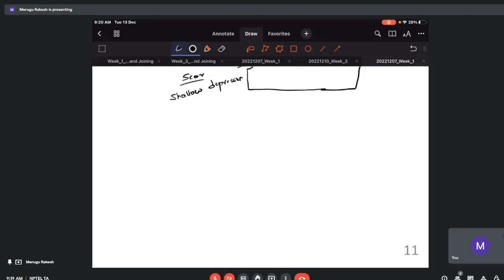So let us come to the final type, the pinhole. So these are a group of small holes within a small proximity. These are narrow deep holes which are formed mainly due to hydrogen gas. So the reason is similar.